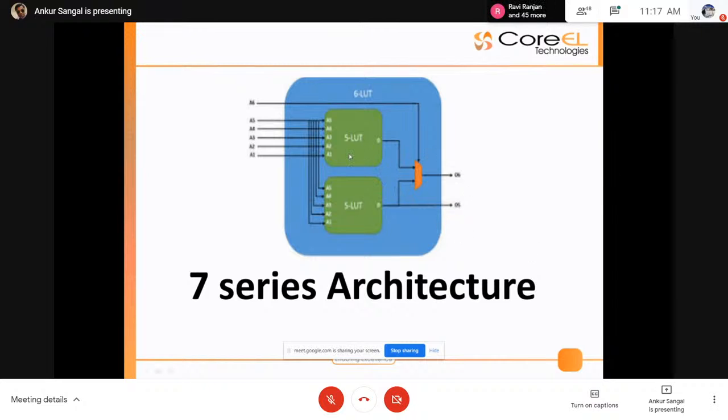With the help of one 5-input LUT, you can easily implement your sum equation, and with the help of another one you can implement your carry equation.